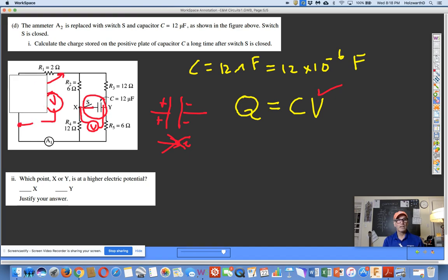So I'm going to take my voltmeter and go from here to over here. That's 20 minus whatever the voltage drop across R1 is. And I charted it, so I know it. I don't remember it off the bat, but we'll go back there. Then you go here, and if you put that voltage here, you're going to go 20 minus V1 minus V2. And that gives you the voltage in this vicinity.